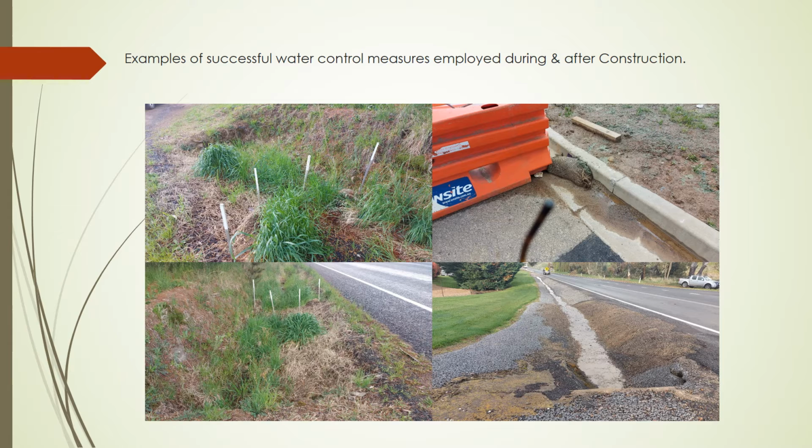And pictures right, you're actually seeing 2 completed situations where another temporary sediment control measure has dropped out some quite coarse sediments before they've reached a drain point. And picture right lower, you're seeing a well completed drain where they've used coarse faced concrete to help slow water rapidity so that it doesn't tear into the Blackmans Creek at the bottom. It's slowing down and is effective.